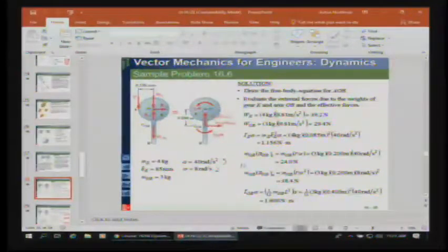All right, so then we're going to take the mass times the acceleration of the center of OA, in the tangential direction, and we can compute the mass times acceleration by taking mass times a radius. Now, if you take a look at this radius, we're talking about the distance between here and the mass center here, or where that is going to be acting on that arm. Okay, and then we just come out with an expression for this, which is the tangential component of the inertia vector, and this is the normal component of the inertia vector.